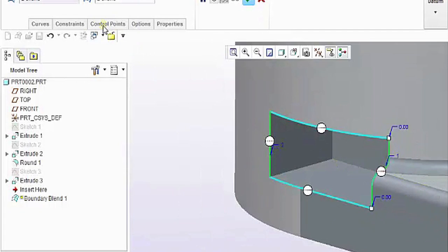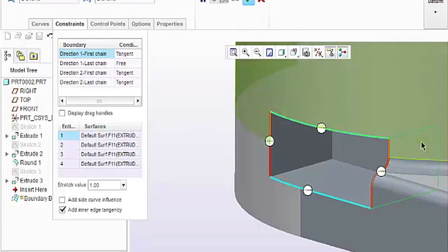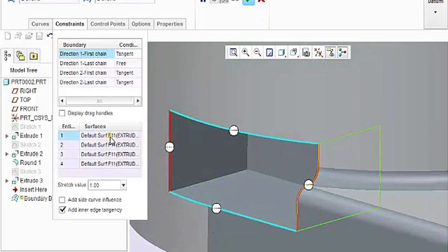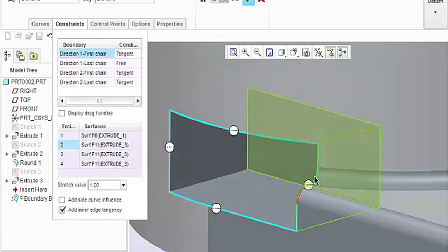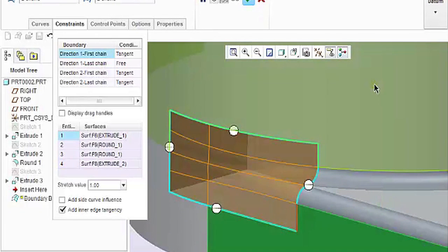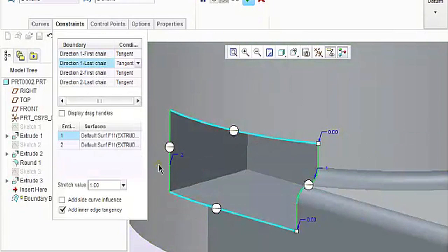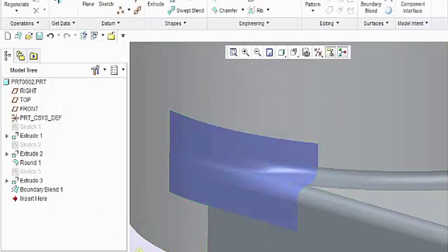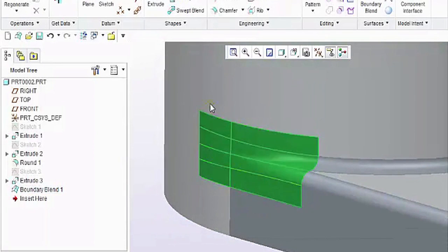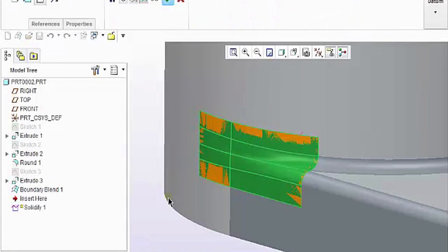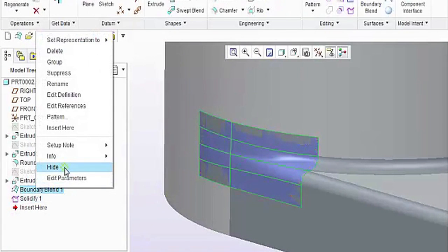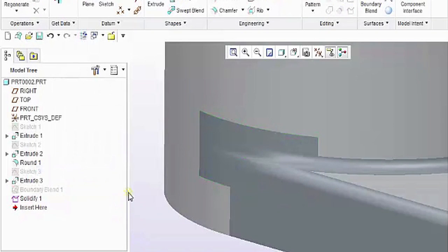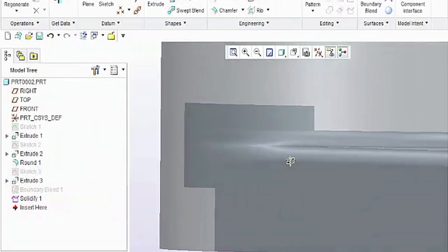This one went tangent to those edges and doesn't work, so I'm going to come down in here and be more specific. Creo basically flipped a quarter on what it's going tangency to. Do you see what's red? I'm going to pick that one. Notice it went to the second notch. 2. Notice it skipped this one because it's not involved anywhere. 3 and 4. Let's force tangency over here. It's got confused again. I expected it to get confused. And there we go. Patchwork. Let's solidify that geometry and hide the original surface. I usually manage this with a layer by hiding all the layers, but for the example, now I've got a smoothed out kind of area.